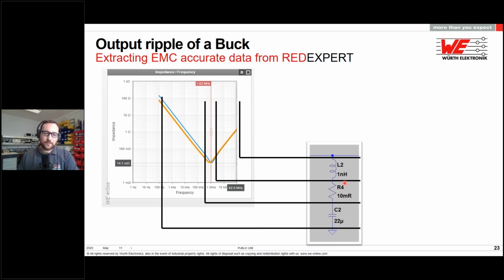It's not the actual value of a capacitor, but it's the parasitics, such as the ESR and the ESL, the parasitic resistance and the parasitic inductance of the capacitor. So in the first region that you see here, we've got the value of a capacitor that makes the impedance go lower with frequency. Then we reach a minimum, which is usually the ESR, and then we see that our capacitor has an impedance which is growing with frequency, and this comes from the ESL.